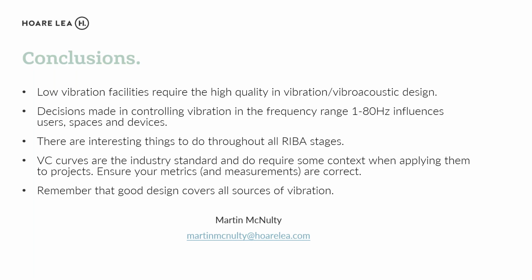There's interesting things to do and challenging things to do throughout all the RIBA stages. VC curves are the industry standard, but bear in mind they do require some context when applying them. So ensure that your metrics, your client discussions, and importantly your measurements are correct. And a good vibration design includes all sorts of vibration, not just environmental, but also internal too.